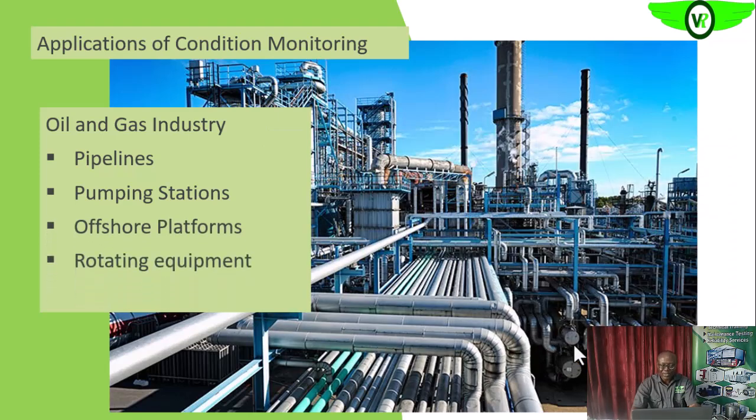Then on offshore platforms, which is a summary of all that we have explained before, we can use all of those technologies. Then rotating equipment, like we said before, is one of the areas where we apply vibration analysis and oil analysis, so that as the condition of the equipment is deteriorating, we will see it before it deteriorates to failure stage.